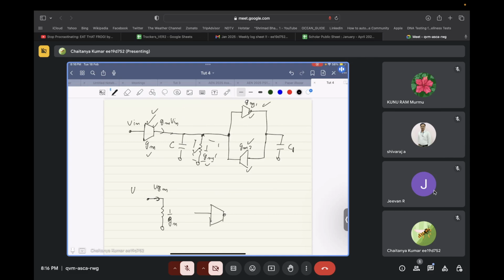let's say you had this thing over here, a transconductor of a value GM. So if let's say V was given over here, what will be the current that will be flowing in this direction, ulta? If there is a bubble, this is a negative transconductor, so V times GM. So you want this current to flow from this node, and mind it, since a transconductor is a voltage controlled current source, while sensing the voltage, you always want high impedance.